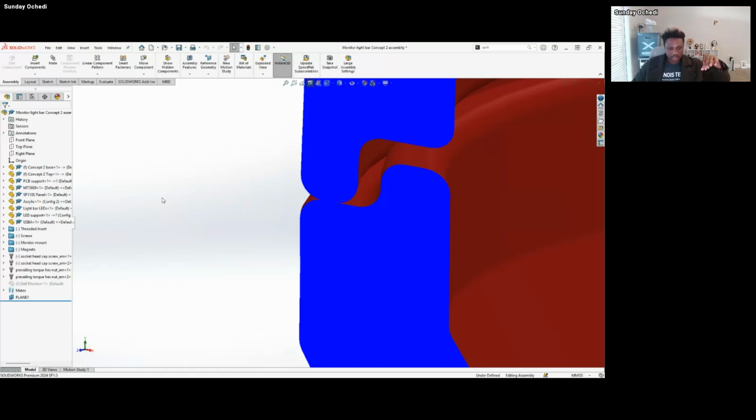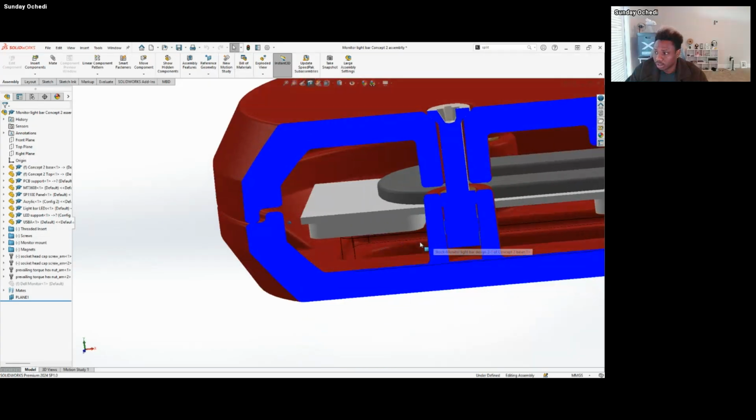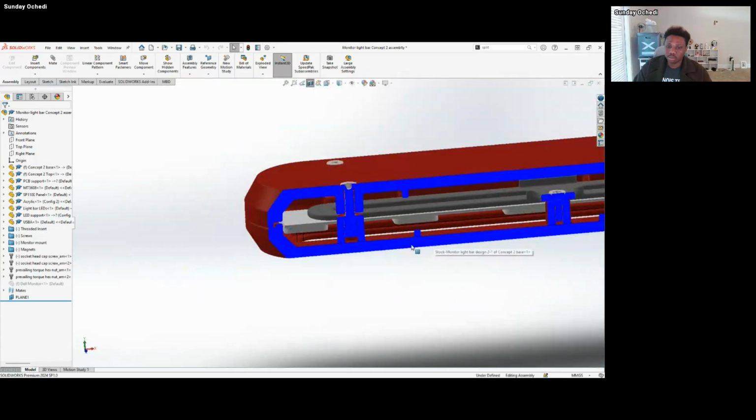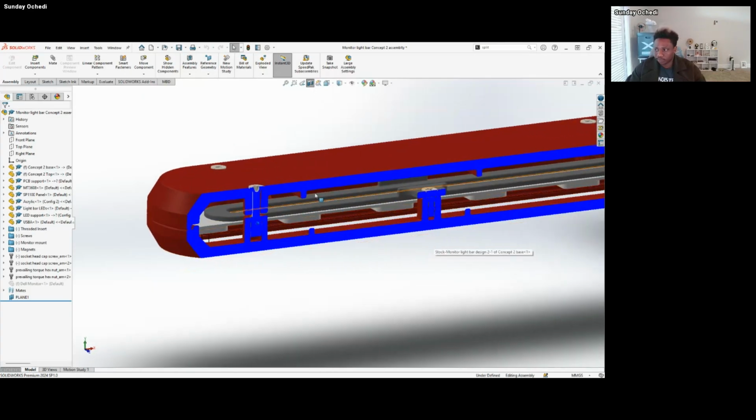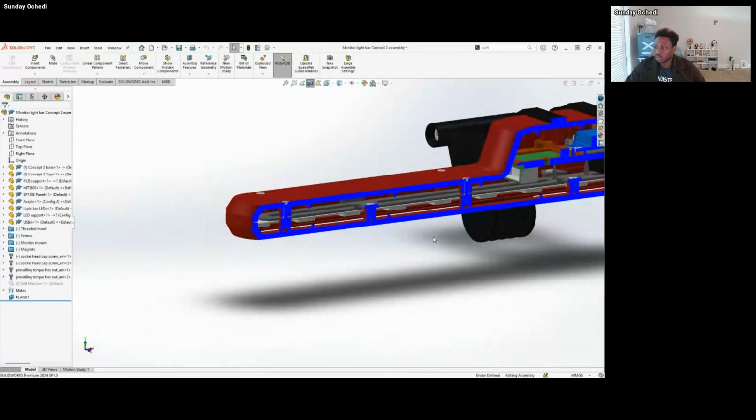You have the tolerancing issue to consider. So based on your machine, you know if it's going to make less or more, and that way you are able to increase the size slightly to ensure that when the part goes in, it fits there and just stays in place. So that's kind of how the terminology flows around, and you get to understand more when you work on 3D printed parts and see how they fit together. You get to understand more about it.